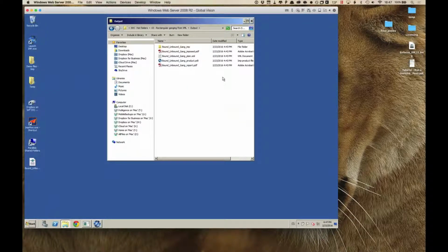And that allows you to do a combination of fully automated ganging, where the majority of the process is handled automatically by IMP Flow, but where someone with IMP manually will check the result of that imposition process and make sure that the files are actually all good before they are sent into the rest of the workflow. And if something needs to be changed, you don't have to restart the whole process. You just open it up in IMP manual, do the changes that you want, and export the imposed PDF or JDF from there.